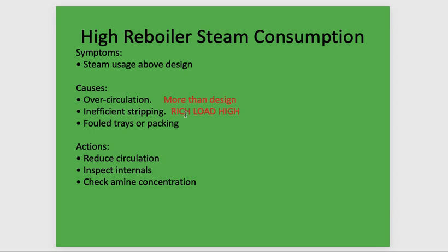This means that when you receive the rich amine, which carries over more H2S and more sulfur, you have to make a comparison between the rich amine load coming to the unit and the design, because each unit works with a specified design, not for granted. So when you make this comparison, be sure that your rich amine is not loaded more than the design.